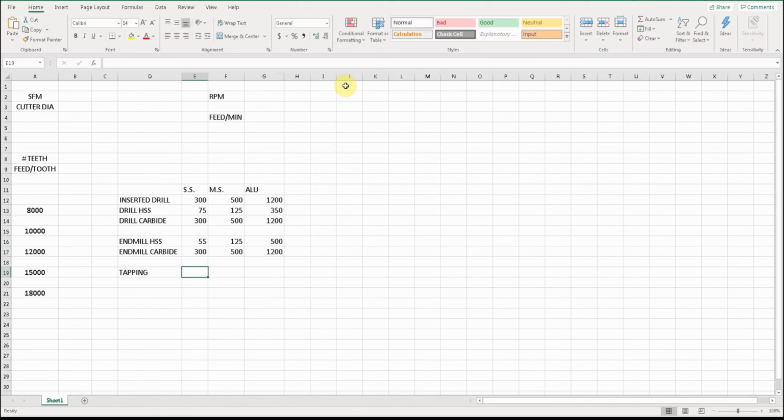These started out, they came from the Machinery's Handbook, is where I started getting these numbers originally. And then I've been slowly adjusting them. So tapping, stainless steel, you probably want to start around 15, depending on what kind of tap. Manufacturer's recommendations are always best though. So mild steel, nah, we're gonna go 50. Then aluminum, go 150. Let's call it 100. 125 just to be safe. Alright.